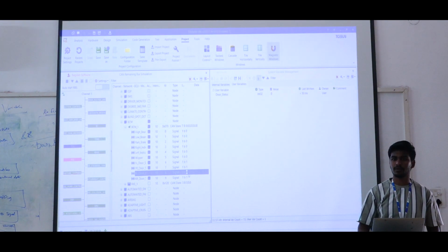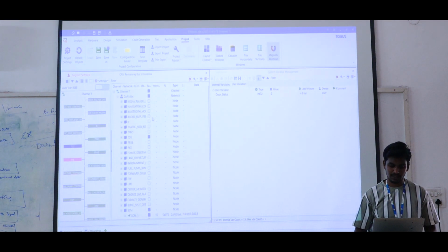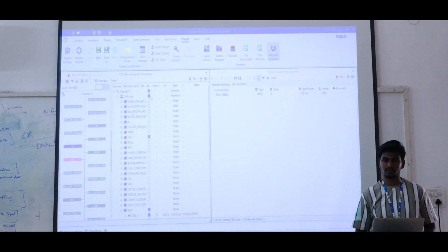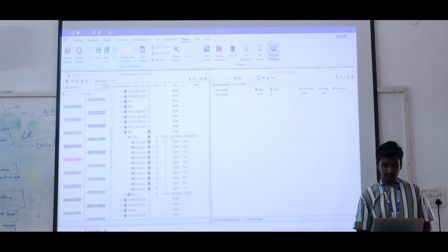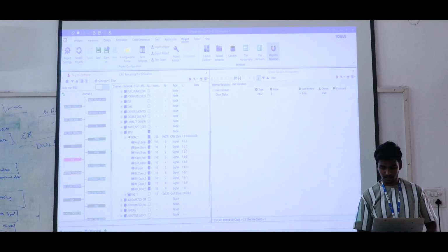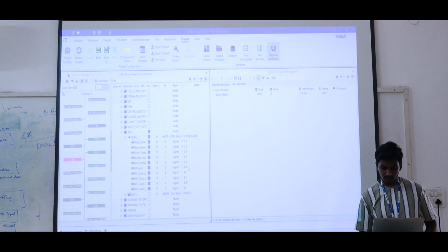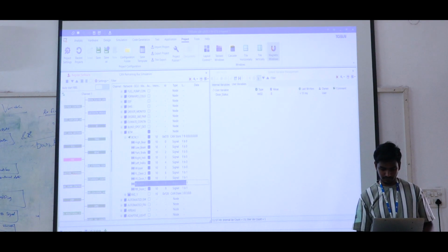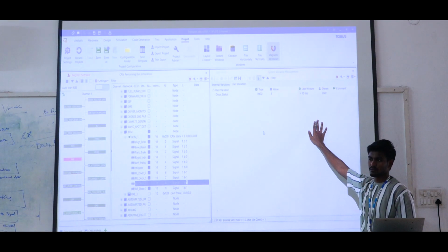For that, open the rest-bus simulation, connect the main rest-bus simulation, and please check whether the database is active or not. If you previously opened any other topics, you can deselect them, that is not an issue. Just turn on the BCM node and then the BCM message. For the last 4 values, you have to enter 1 for all 4 data. Only then will the door status be 1.